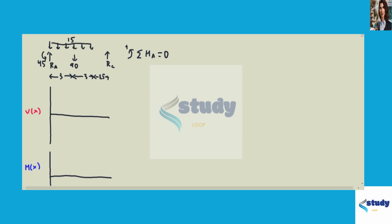All right, we've got our 45 applied minus the resultant of the distributed load, 90 with an arm of 3, and then we've got our reaction at C with an arm of 7.5, and setting that equal to 0, we will get our reaction at C equal to 30 kilonewtons.